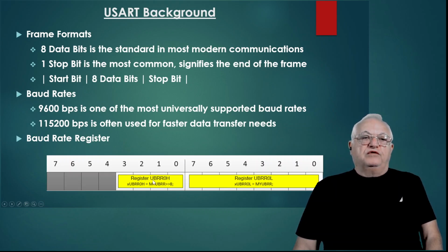So here below shows you what this would typically look like. You would shift your result by 8, and that's what goes in your high bits, and then you would just put the first 8 bits into your low bits.